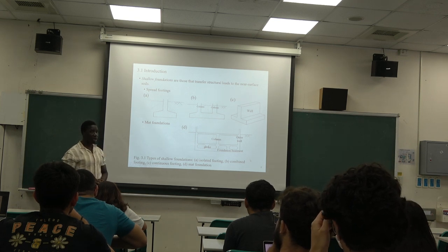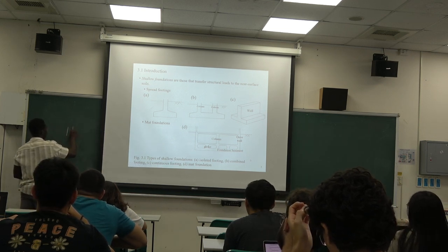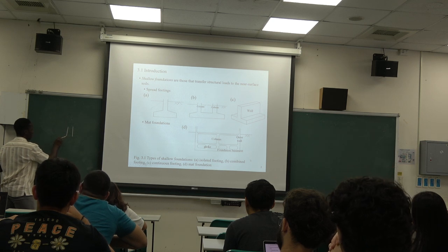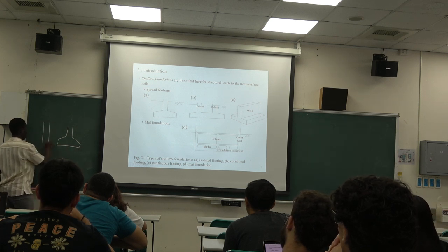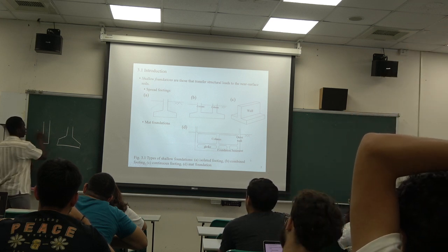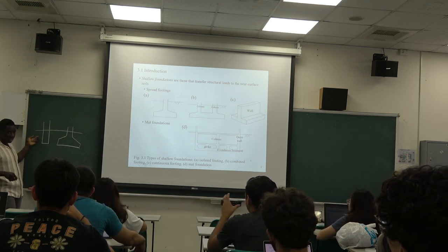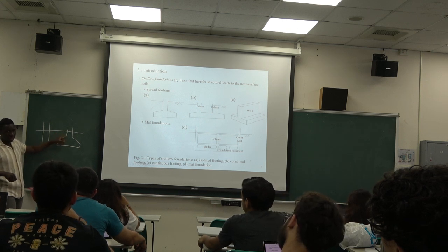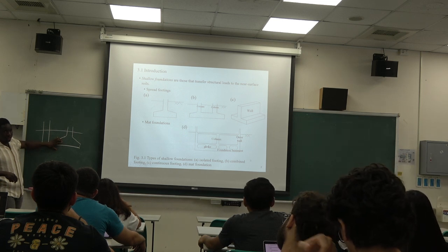Here we have different types of shallow foundations. We have the spread footings and also the mat foundation. Your typical spread footing is like this. You can just put it like this, but we will instead have something like this. Do you have any idea why we will use something like this instead of this? Yes, it gives you more surface area, because we are trying to transfer the loading from our structure to the soil. So when we do this, it gives us more surface area.